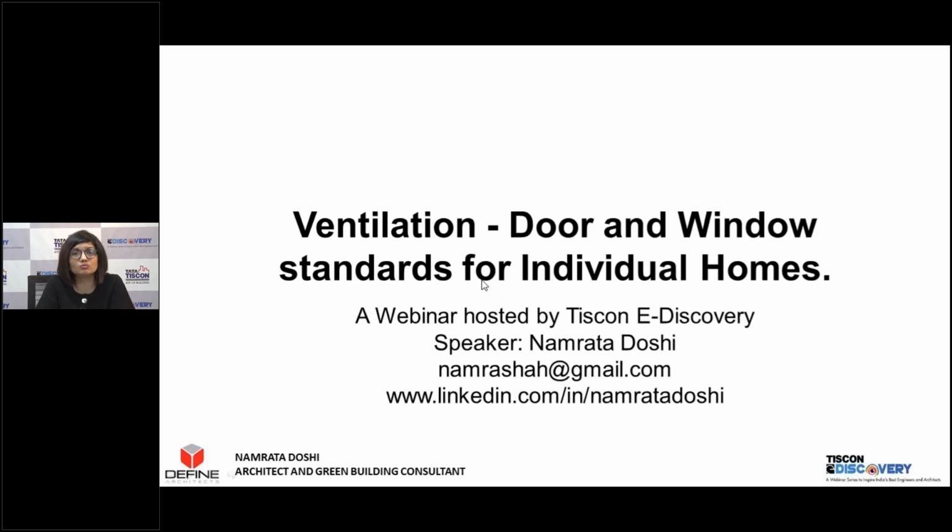This comes back to my segment where I covered what materials can do for your openings. Basically, let's say your opening size is 4 feet and it's all glazing in a hot and humid environment. What you're essentially doing is helping the hot and humid environment to bring the heat into your space because you're using glazing and keeping the entire opening with full glazing.